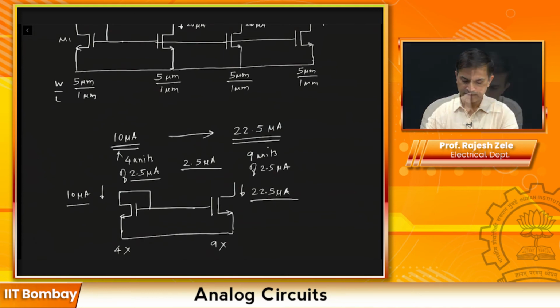Okay, all right. One other nuance I would like to tell you when it comes to analog design, specifically integrated circuit design, is a layout aspect of how you draw the transistors. In the previous example, when you want to get a factor of 10 or a factor of 2.5 or whatever factor, you would drop a single unit cell transistor and then make multiple copies of it.